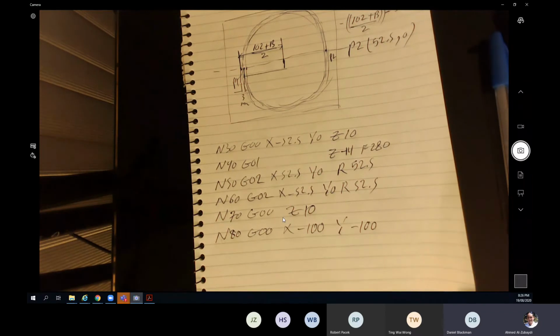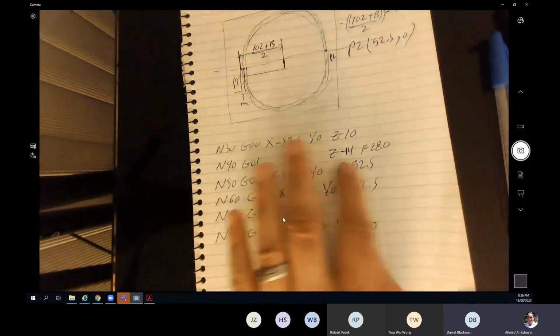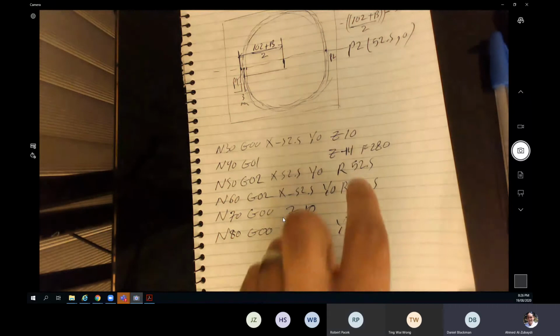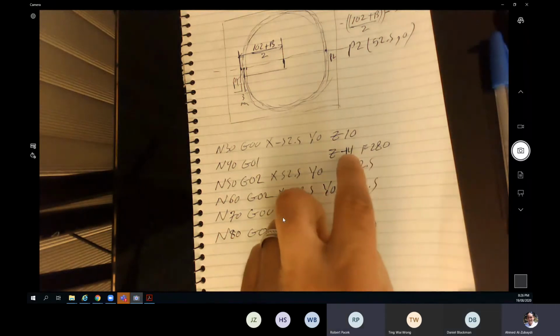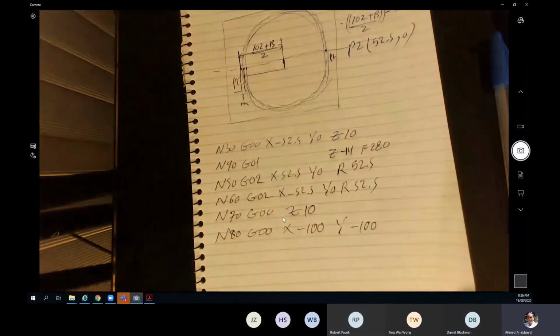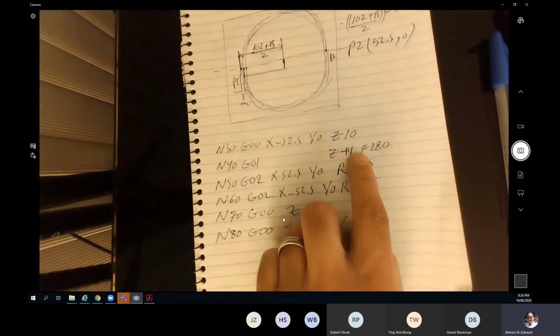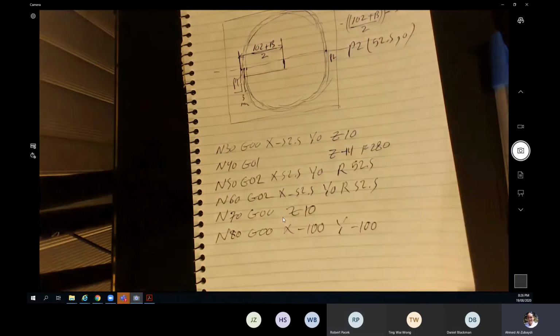Okay, but I'm not going to take marks off if you just did what I've done for shortcutting. Oh, okay. So actually, you can add 1.5 millimeter to all the Z values I used earlier. So this one is going to be minus 15.5 instead of minus 14. For the drilling, you are going to have minus 28.5, instead of minus 27.